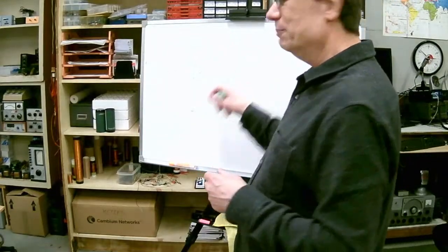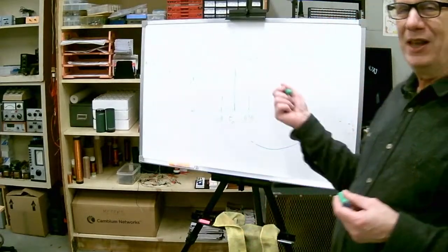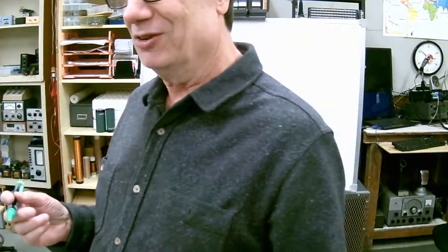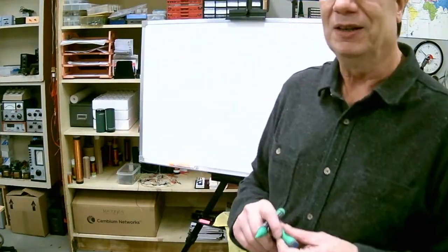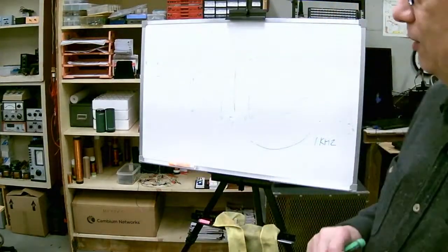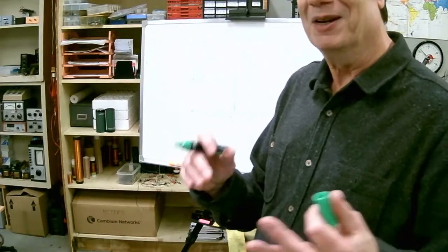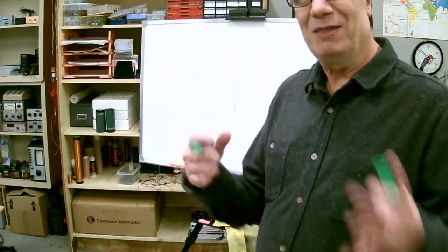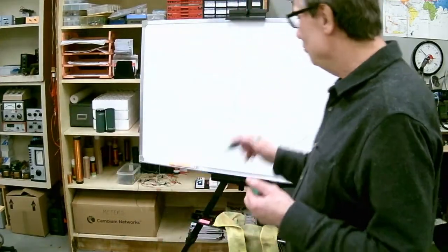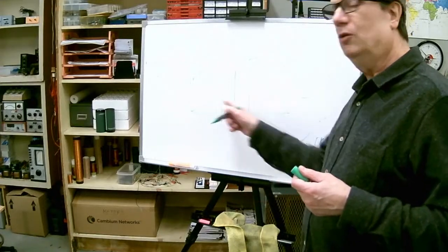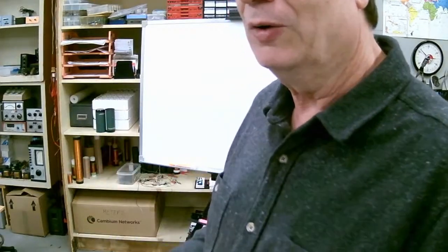Because you need this to demodulate. You can't demodulate without a carrier in there. Now, in single sideband, you add the carrier in the receiver, and then you can demodulate it. But without that, you need all this information in order to demodulate it. Since you're mixing these two products together, multiplying them together, you can run through the mathematics, and it doesn't require high-level calculus, it's just some algebra. You can show that these two power levels have to be the same, and one's above carrier frequency, one's below.